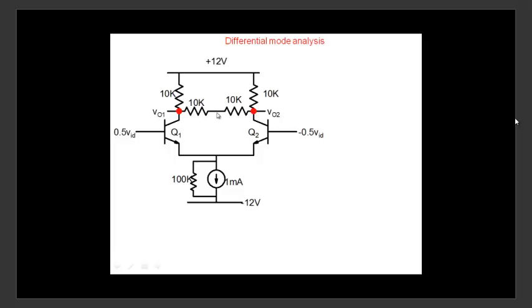So what would happen at the center? 0. So this circuit will become a small signal ground here. This is also a small signal ground here. So the whole circuit reduces to 10K, 10K, and now it's a simple common emitter amplifier you can easily solve. So if the circuit is not symmetrical, try to see how you can make it symmetrical by breaking it up.